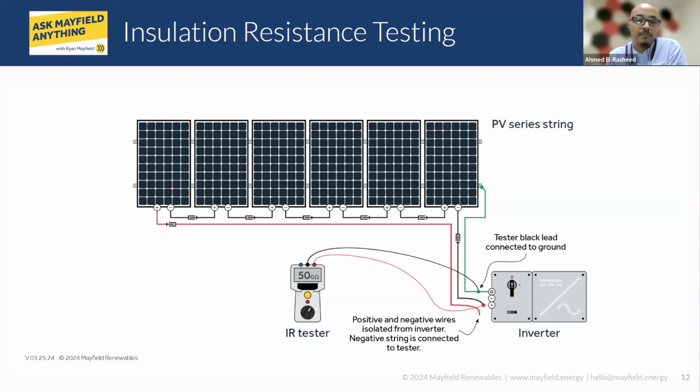And the conventional way of interpreting it, instead of looking at the actual current measurement, is to just take a look at the resistance value. And if that resistance value is low, you have a leak in that insulation, you have a break to ground. And if it's high, then it's holding the pressure well and you don't have a fault to ground.